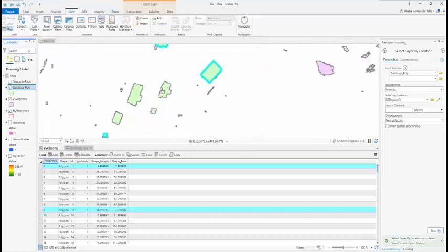Then you can also export this file: right click, then data, then export features. Then you will get a new feature that has only the selected ones. Then you can make a map of both the selected ones, the ones at risk, and the ones that are not at risk together. And that is all about this exercise 3 and some of the errors that you had. I hope this will help you to finish the exercise and submit your task on time.